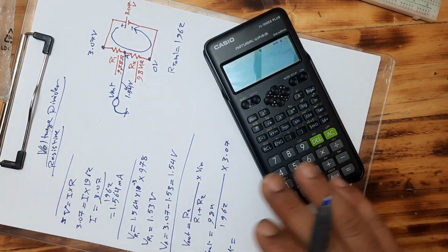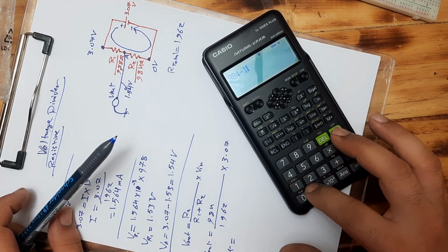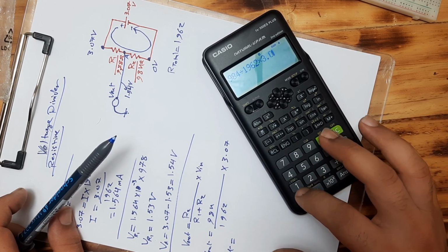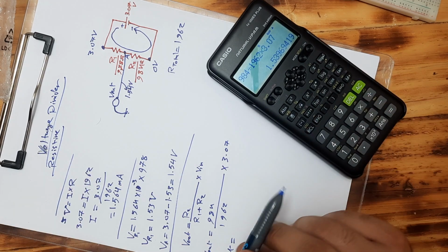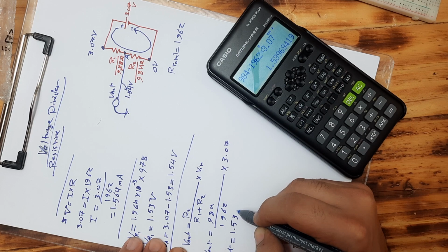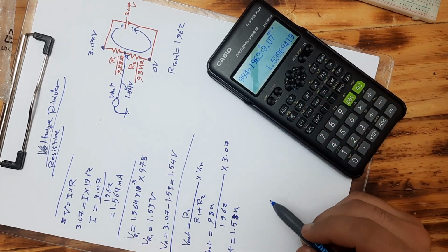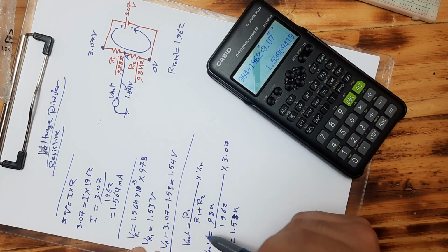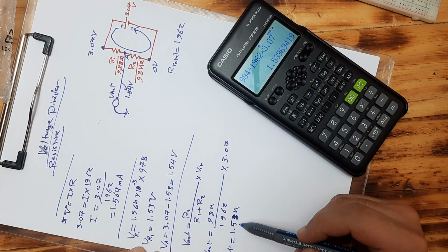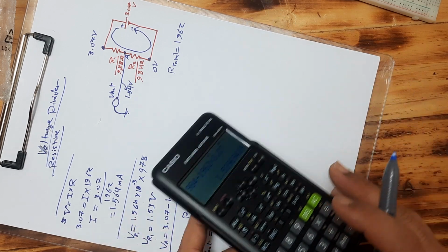So Vout equals, let's do the calculation. 984 divided by 1962 multiplied by 3.07 equals 1.54. Now, if you remember, we calculated that value right here to be 1.54. So you can see this equation makes our life much easier.